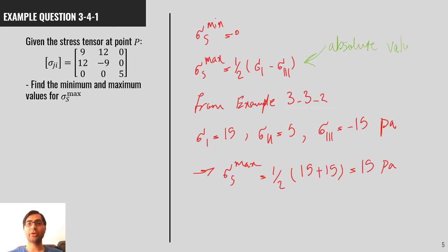We can use this information for design analysis, because some materials fail under maximum shear stress, so we need to find this value, and we need to find this direction because they basically break in that direction, like ductile material. But some materials break under normal stress, so we need to find the principal stress values and the principal stress planes, because that's basically the value at which the material breaks, and the principal stress plane is the plane in which the breakage happens.